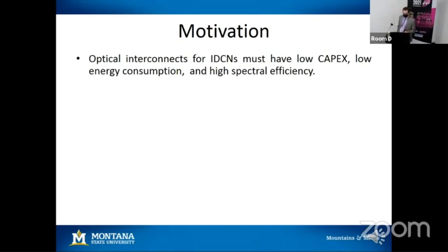In order to increase the spectral efficiency, people try to go away from intensity modulation direct detection, at least the binary part. They try PAM4, but as you know, this is a type of modulation that is one-dimensional. In order to spread points more, we want to go into higher dimensions.